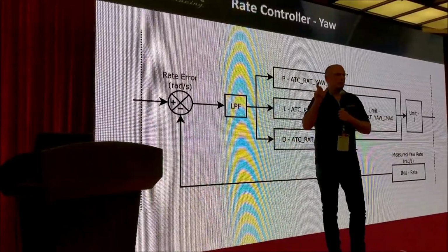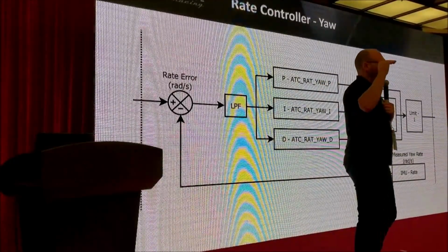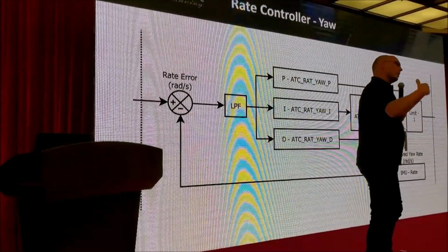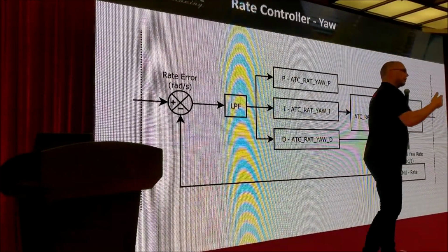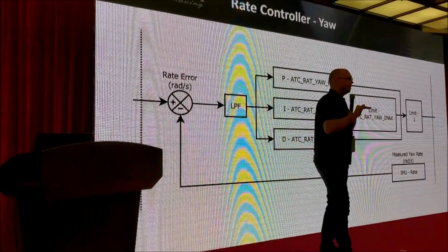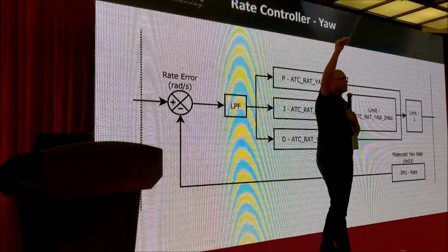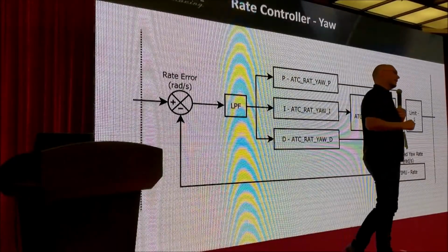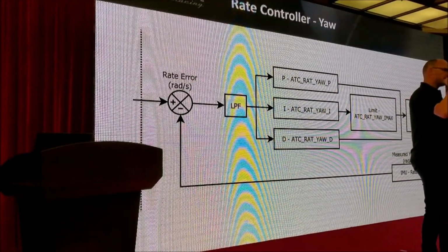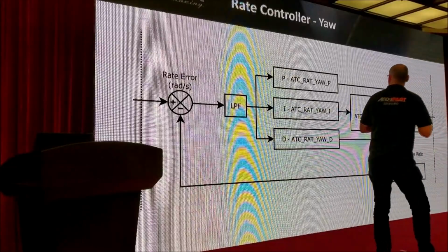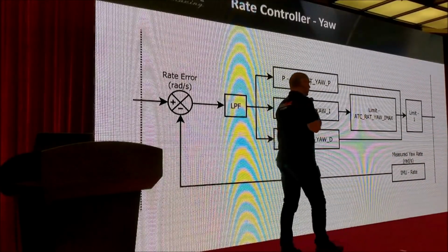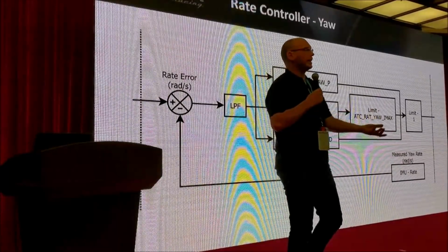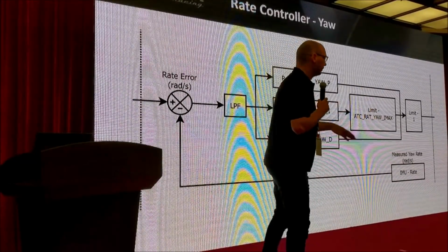When you increase your throttle, the torque on your motors instantly affects yaw. But for roll, pitch, and thrust, it takes time for that throttle to increase before roll, pitch, and thrust start to react. Whereas yaw, it's instant. And so this is like having a mechanically based D term.